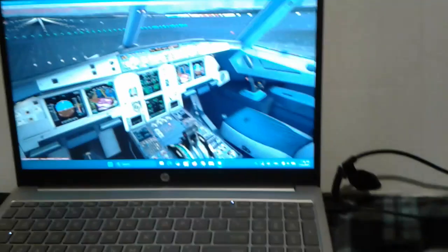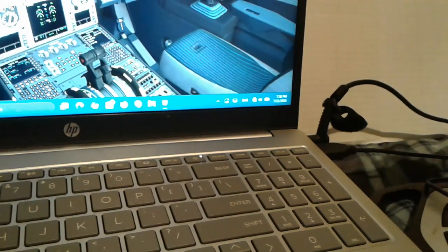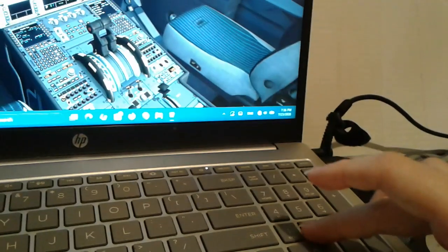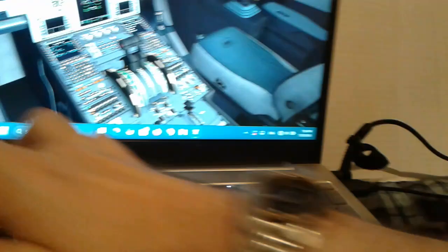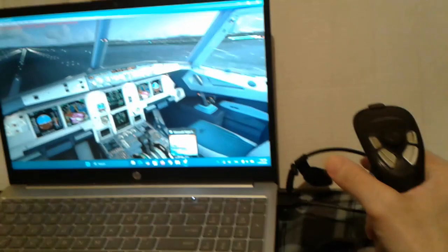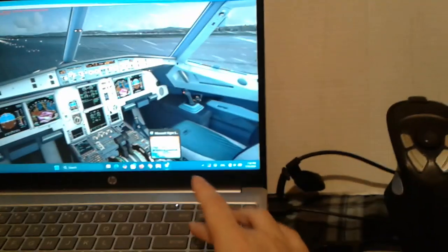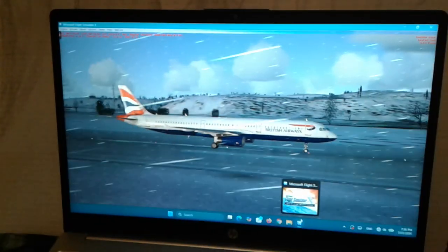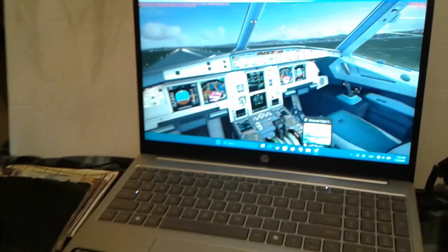The thrust levers forward, parking brakes off. You have to use also the flaps, but for this flight it is okay because I don't use too much weight right now. It's gonna accelerate. So here we are, V1, we rotate it slightly, let it gear up.